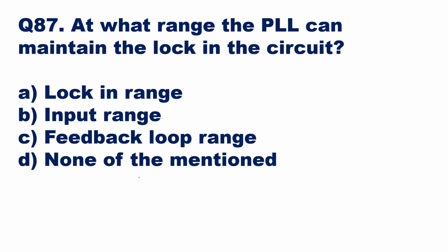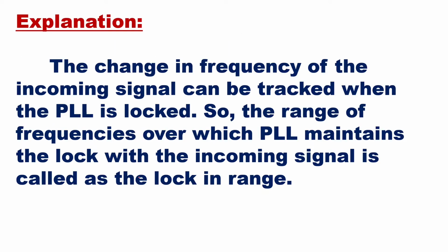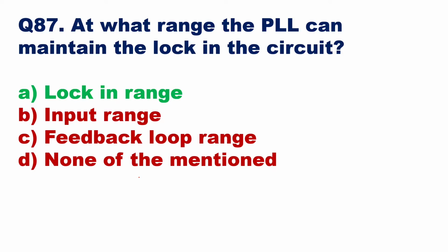That range is called as lock-in range. Okay, so here you can see the explanation. The change in frequency of the incoming signal can be tracked when the PLL is locked. So the range of frequencies over which PLL maintains the lock with the incoming signal is called as the lock-in range. So here option A will be the right answer, as we have told earlier, lock-in range.